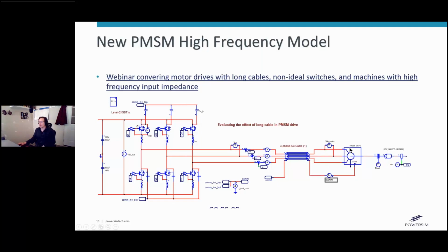And then we're also linking it to the chassis, so we can have the common mode noise issues as well. So we can link all the way back to a common ground, and then we've also got coupling here from the individual devices to the common mode, which would go through the heatsink. So we can model all those sorts of things quite well.